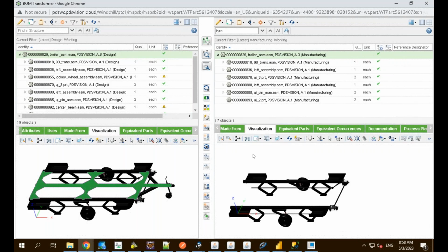Whenever we are at EBOM level, I mean, whenever we are at a stage that we have our engineering bill of material, you can have your manufacturing department come into the picture and create a copy of this EBOM and create a manufacturing view bill of material to maintain and update all data and processes related to the shop floor, such as raw material or tooling, jigs and fixtures and all such data. You don't have to put that specifically on your EBOM because it's not necessary to put that information on EBOM, since it may differ on different plant locations also.